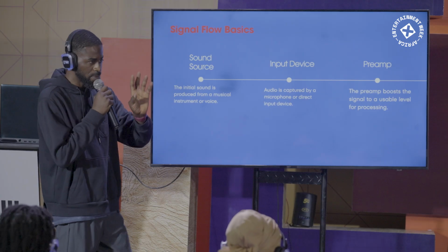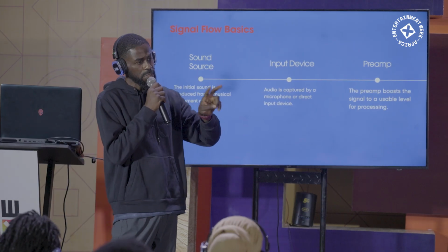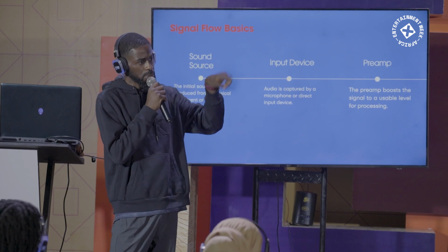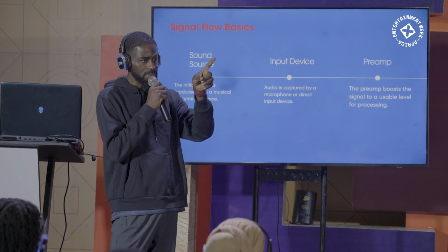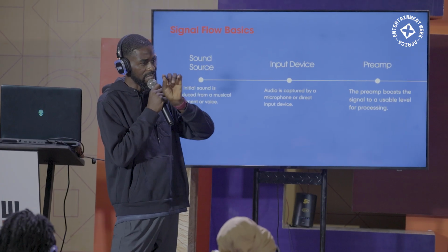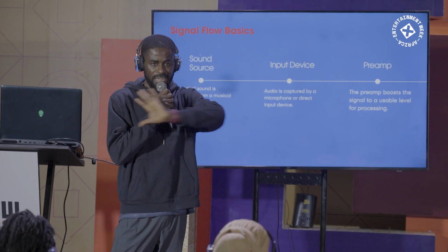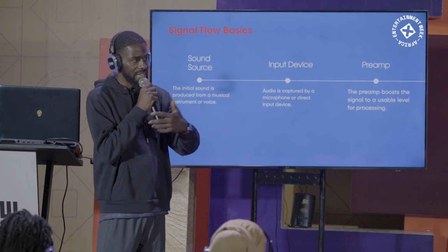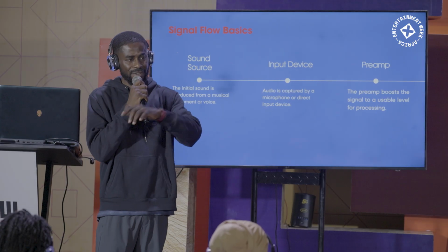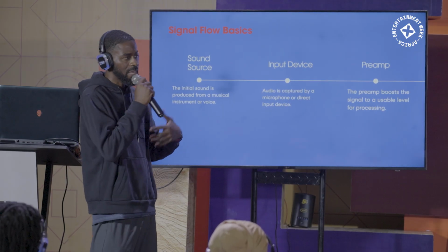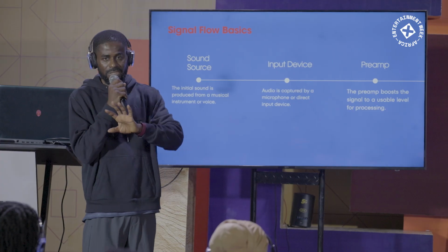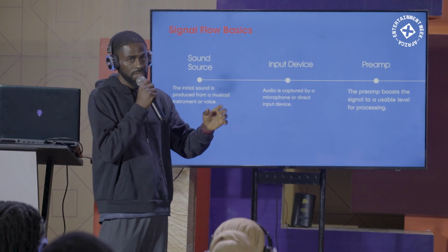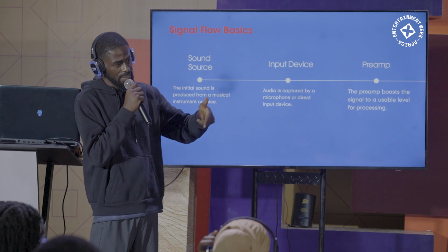Like I always said, there's a rule to sound, right? Once you can understand that in sound, it works like this: out to in, in to out. It's never out to out and in to in. You can work anywhere because most of what we do in sound is connection. If you don't understand that principle, it will be very, very difficult for you to go out and connect a piece of equipment. So you have to understand that the signal flow, or the signal patch, for sound works as out to in and in to out.